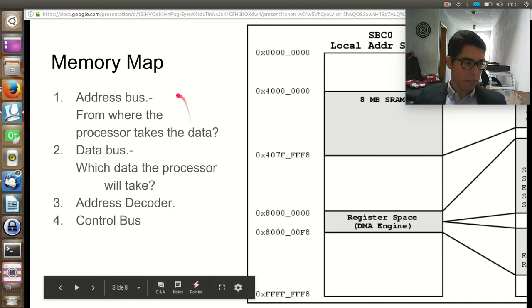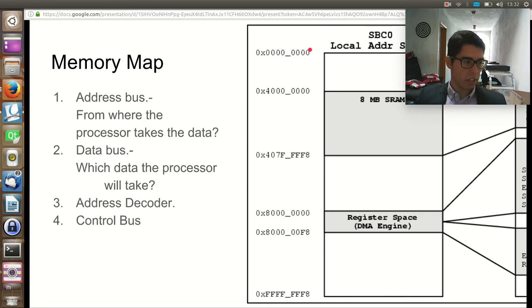So you might have a certain space between 0000 in hexadecimal and 4000. The chip select signal will be triggered if you have, say, 10 hexadecimal, which is within the range of 0 and 4000. So that's kind of the point.